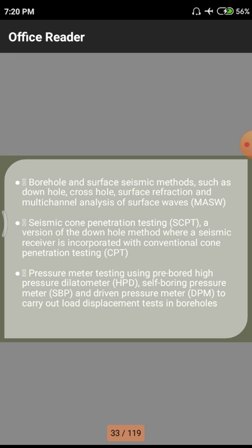After testing with the seismic cone penetration test, we obtain some values. By using those values, we analyze for those particular soils what foundation thickness we need to maintain, at which depth we have to lay our foundation, and what the minimum width and thickness should be. What dampers do we need for these kinds of seismic accelerations? We need to analyze like that.